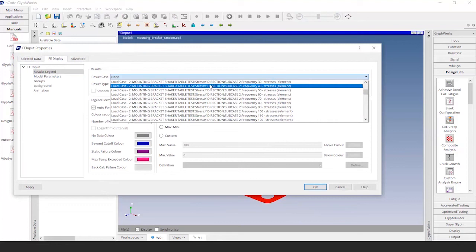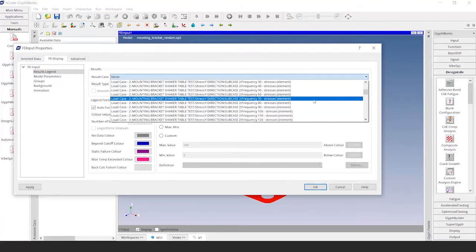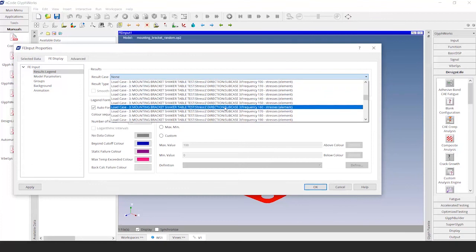And as soon as those are done, we then start back up in the Y direction, 10 Hertz increments again, and then we see the Z direction. So this particular model, in fact, contains excitations in 3 different directions, but for our first demonstration, we're only going to be using one of them. We're going to focus on the Z direction. It happens to be the one that is most damaging, so it gives us the most illustrative damage contour plot.